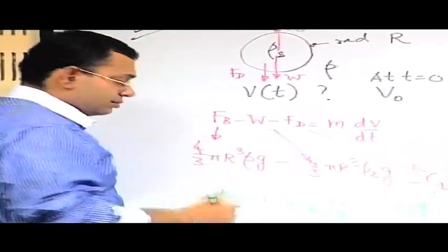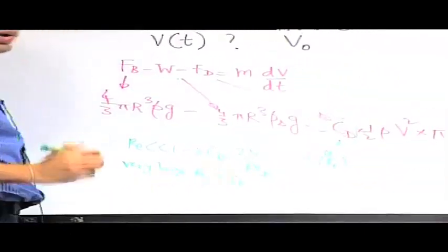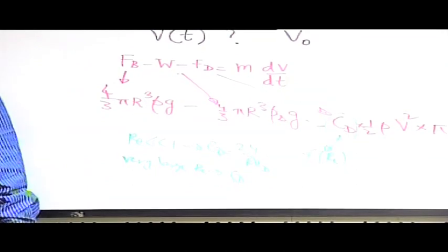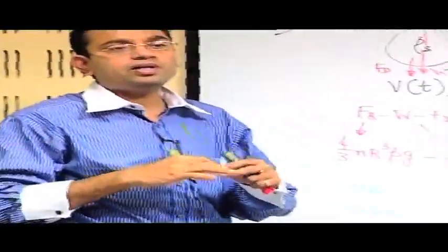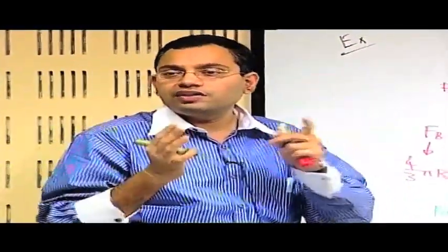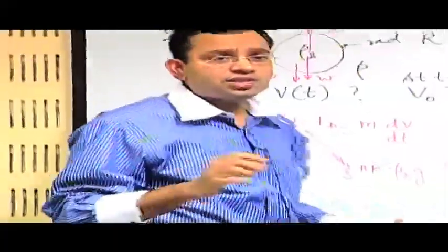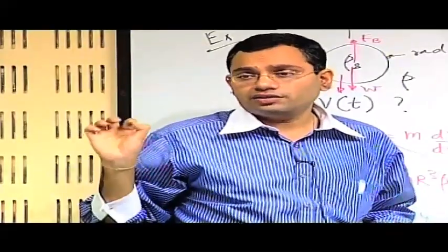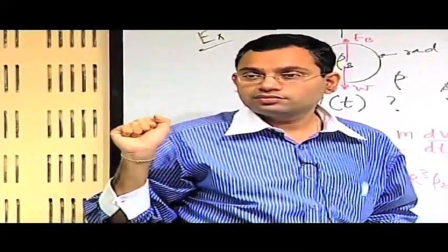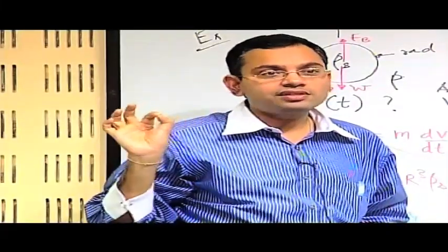If on the other hand the Reynolds number is very large, CD may be approximately a constant independent of Reynolds number, because at very high Reynolds number we have seen that the effect of the form drag for bodies with curvatures becomes more and more important. The reason is, as you increase the Reynolds number, what happens to the boundary layer? Does it become thicker or thinner? If you increase the Reynolds number, the boundary layer becomes thinner.